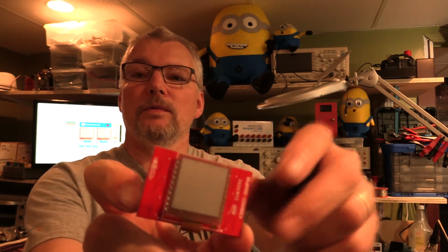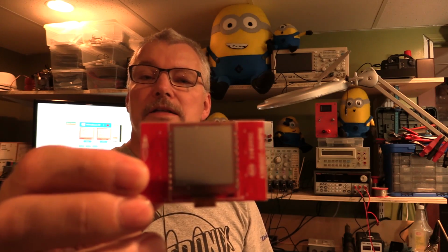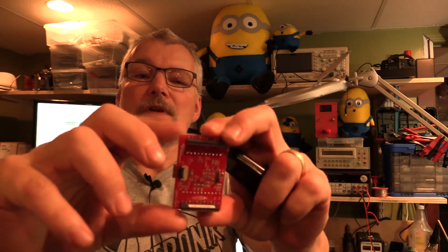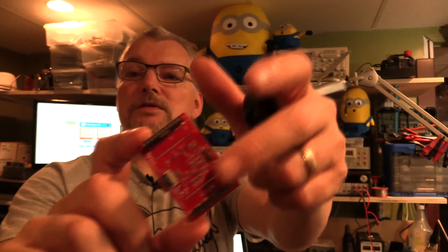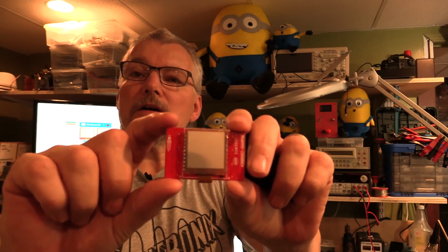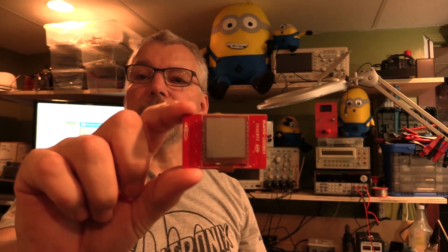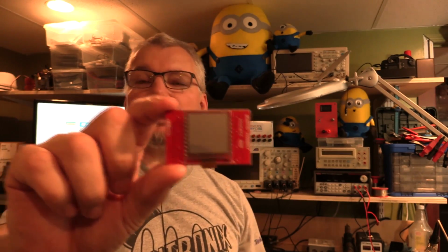Hi, it's me now. Normally I get myself on the screen right at the beginning. So this is the actual display that we're working with here. It's a little thing. It's a Texas Instruments booster pack. Like I said, it's the Boost Sharp 96 little thing, and that's all it is. It's got a little bit of buffering there if you're running it off of a different power supply, and most of the circuitry in the back here actually isn't used. It uses a SPI clock, MOSI, which is the output SPI data from the CPU, and plus 3.3 volts and 0 volts, and that's pretty much it, except for the chip select, of course.